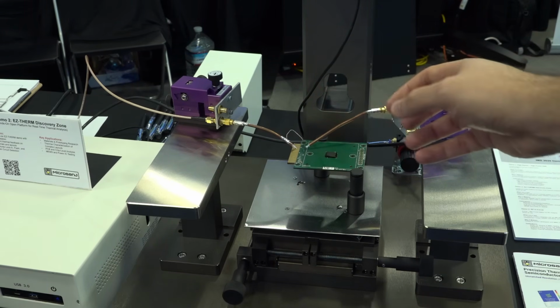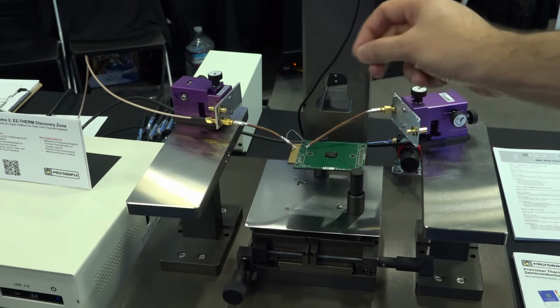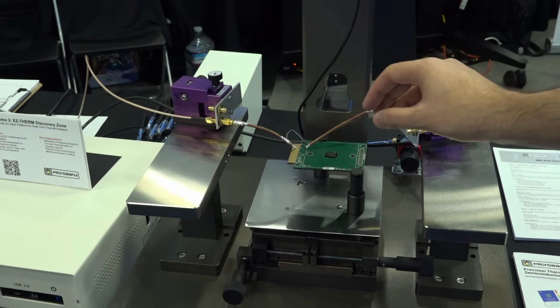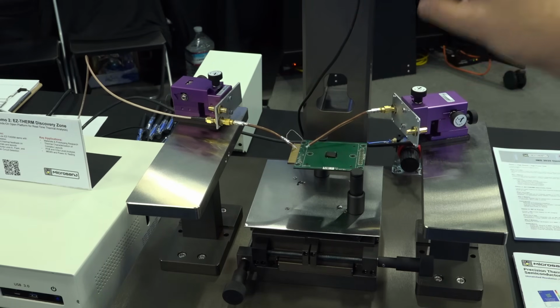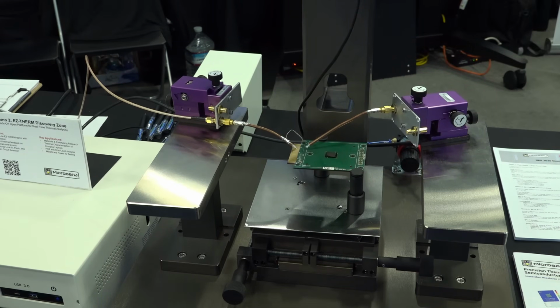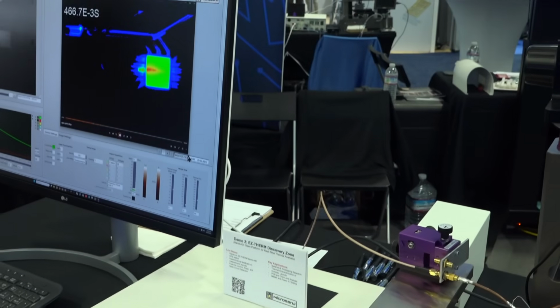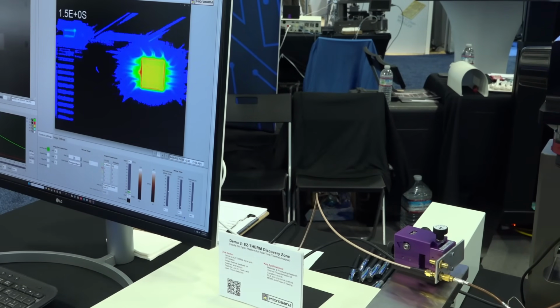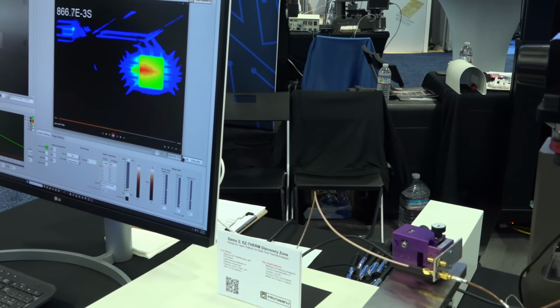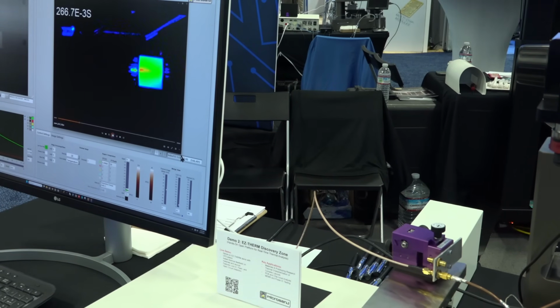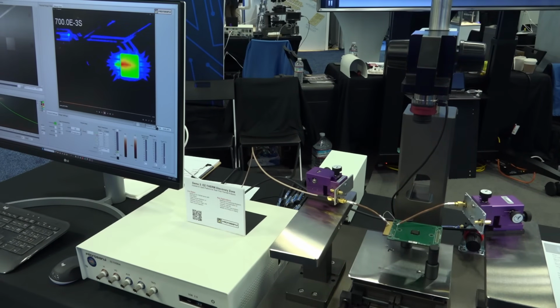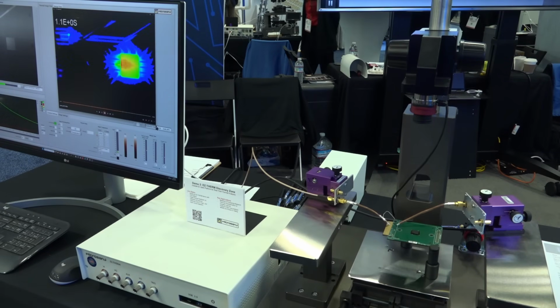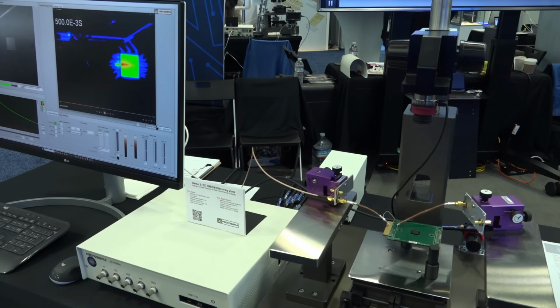Now, if you have an open circuit, the dissipation of that thermal will be different on a circuit that's actually making connection. Now, remember, we're talking about minute differences in temperature. So the measurement system now has to be able to resolve extremely small changes in temperature. But if you can do this, now you have a completely unique way of measuring flaws and disconnections in your system. You're looking at a thermal signature of a physical problem by exciting the circuit and looking at what happens. There's a lot of really interesting things that Microsanj does by doing this kind of signal processing, and I'm eager to get my hands on one of their thermal reflectivity systems so we can cover both the science and what you can do with it in a real environment.